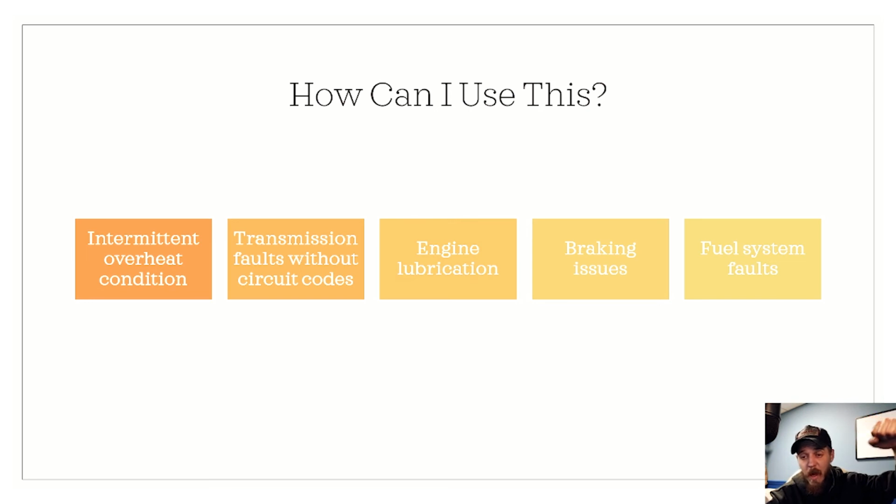That 1800 psi acting on a large piston then fires off fuel to an even higher pressure because it's on the smaller side of the piston, allowing us good injection, allowing us good flame front propagation, allowing us low engine noise, lower emissions, higher power, more reliability. So once again, understanding basic hydraulics, we can diagnose engine lubrication, we can diagnose low pressure oil, we can diagnose high pressure oil, which we can then use to diagnose the base injection system, as well as diagnosing the low and high pressure fuel systems, all with some very basic concepts.